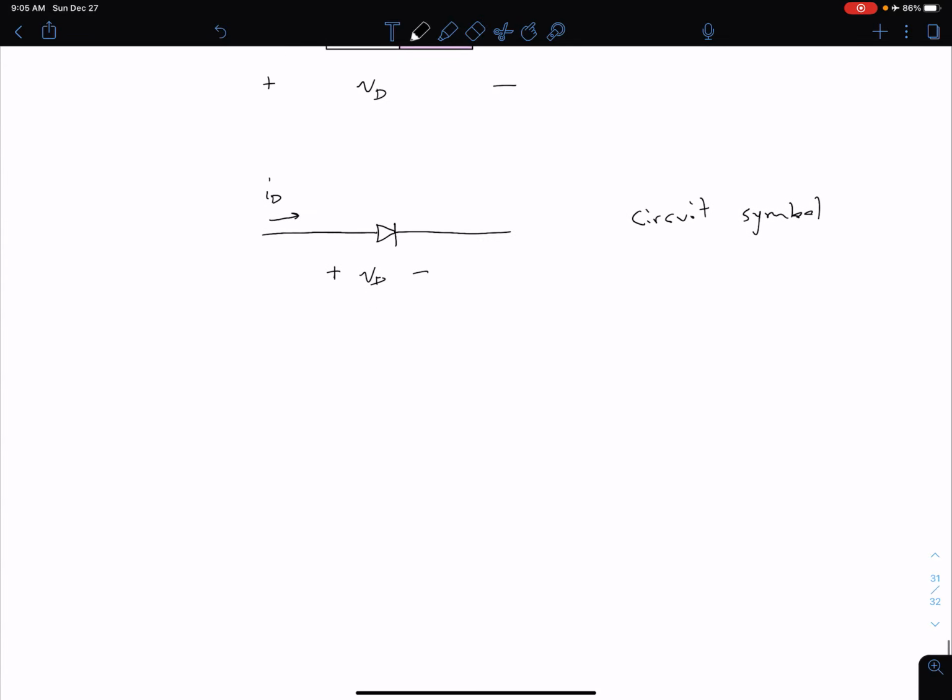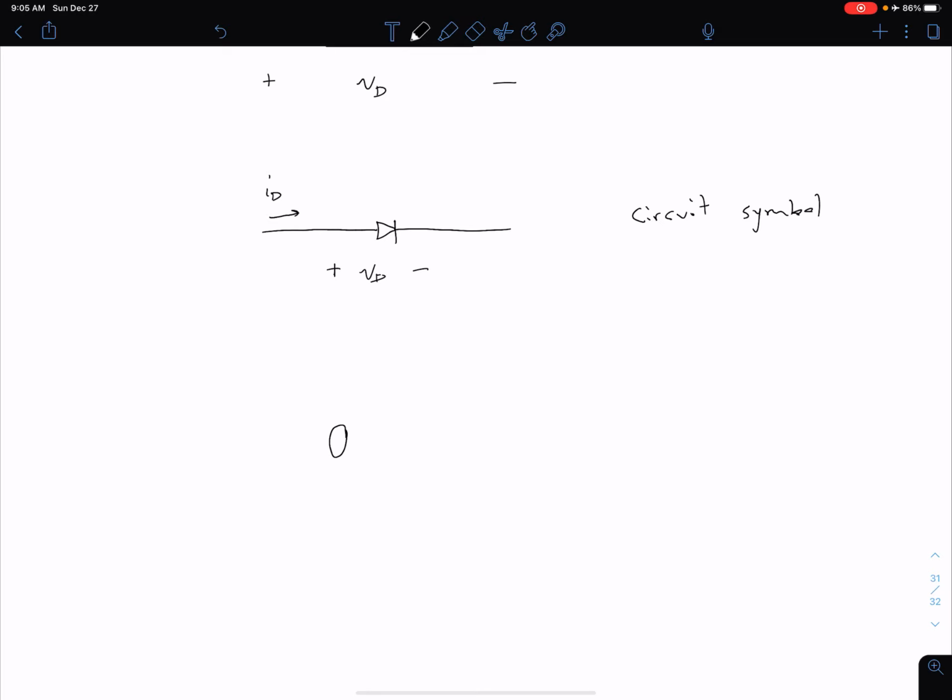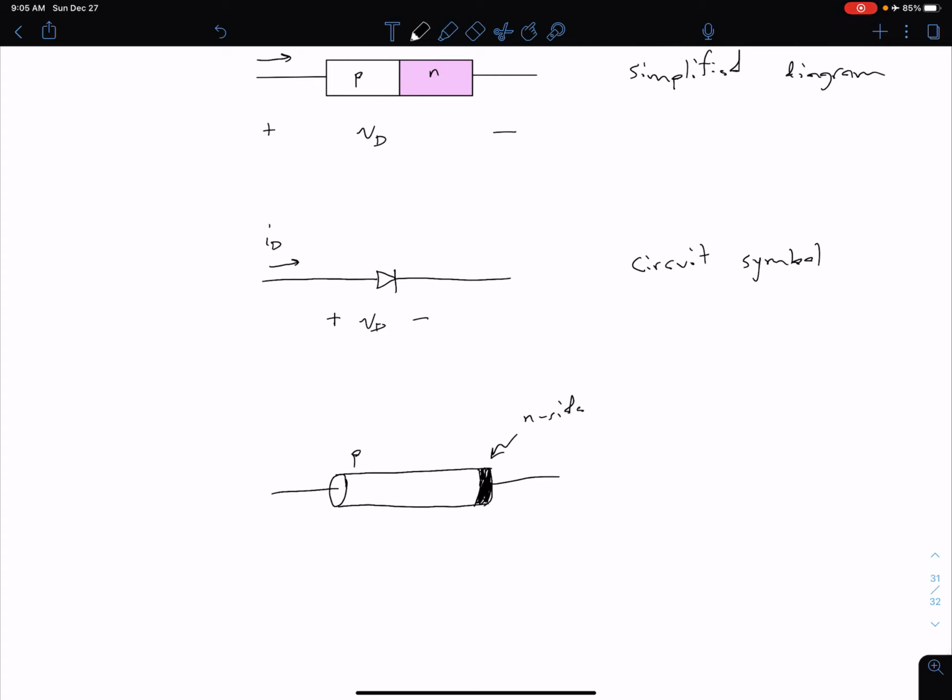What do these diodes actually look like if we go to pick them up in a lab? Oftentimes they're going to be cylindrical. So let me draw this decently here. We have something that looks like this. And then on one end, we're going to have a shaded strip around our cylinder. That strip indicates our N side of the device, and the other end is our P side. That can help you orient it, because this device won't carry current in the same direction. It doesn't operate the same if it's placed in backwards versus forwards, so we want to make sure we have it oriented appropriately.